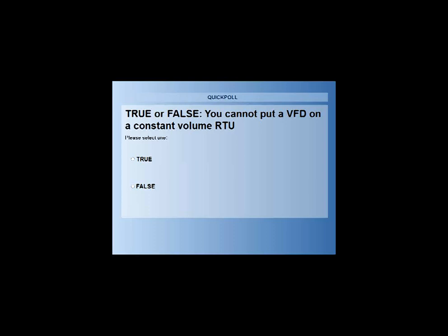Let's see, maybe I can knock out one of the audience questions while we're waiting for that. Jonathan asked earlier, does a rooftop integrated with ERV have a separate exhaust airstream for restroom or other required exhaust air, or does it remove a percentage of the return air? You could do it either way, Jonathan, but for the most part, removing a percentage of the return air is the typical means for that happening.